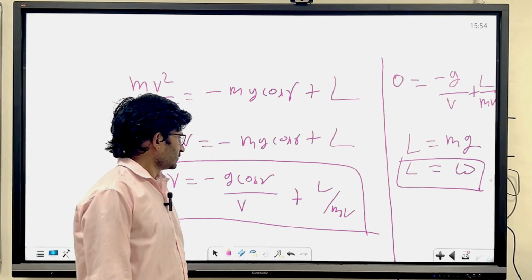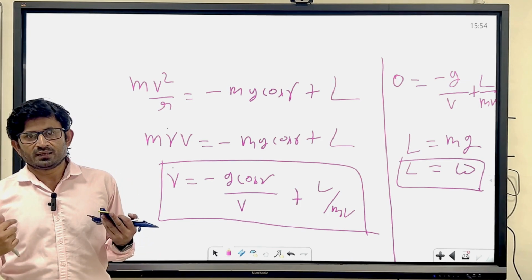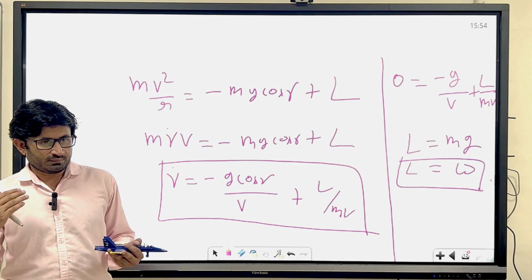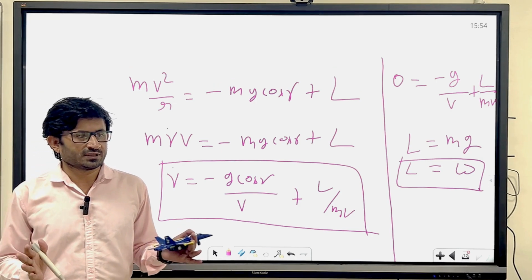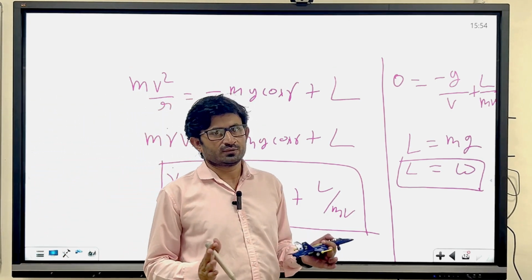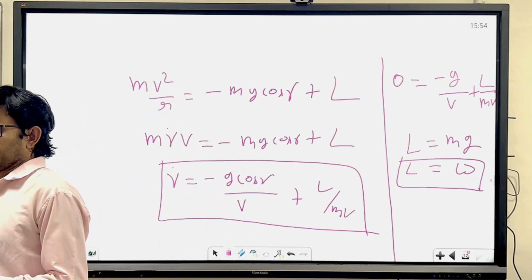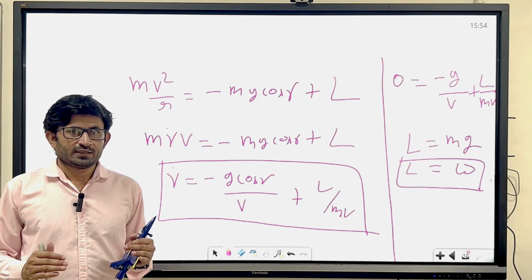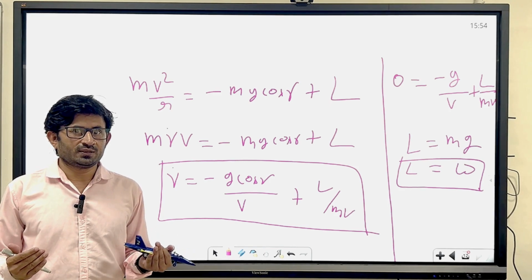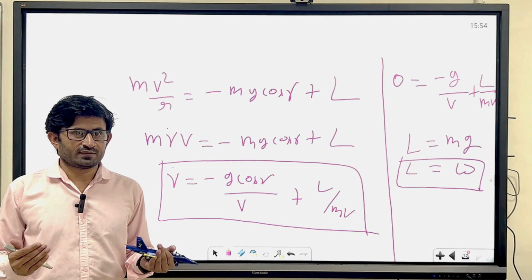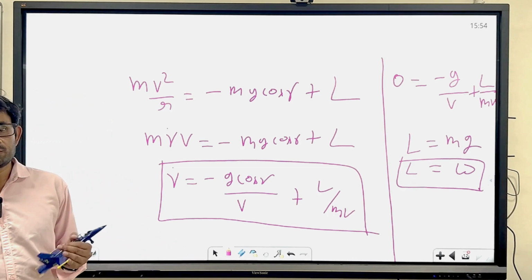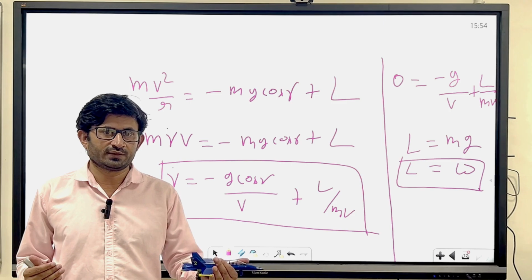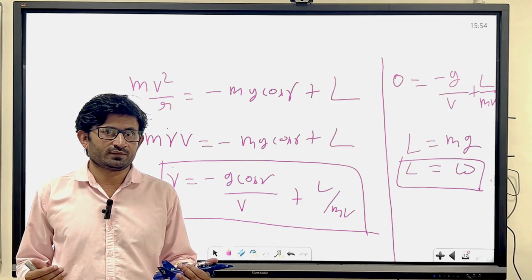So how beautifully you are using lift and how beautifully you are using drag, how you are balancing the weight, that comes under the flight mechanics and control part. Sometimes you need a drag to stop the motion of the aircraft, and sometimes you do not want a drag. For example, if you want to fly at a steady state level flight, we want less drag, but during landing we want more drag to cover the shorter runway.